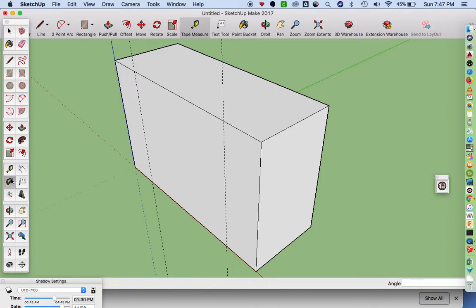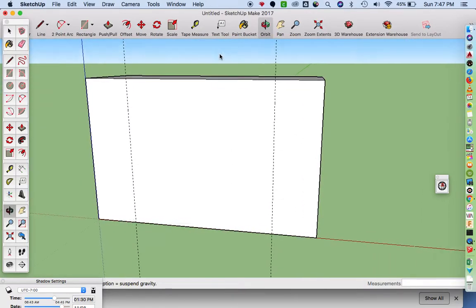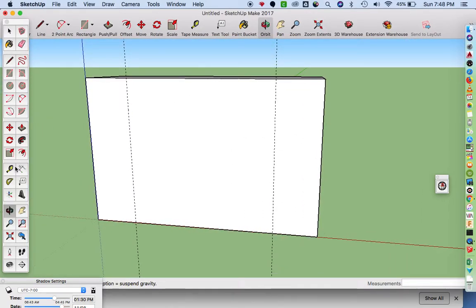Now I'm going to go ahead and find my protractor tool. It's right here. I'm going to make sure that it's green. If it's not, see how it's going to the blue, all you have to do is change your orbit, bring the horizon down a little bit, and then it should stick on the green. Click, come across, anywhere you want, and then go down 45 degrees. I typed it in. Again, I click one time to place it, I drag across, click again a second time, but just once, then drag down 45 and press return.